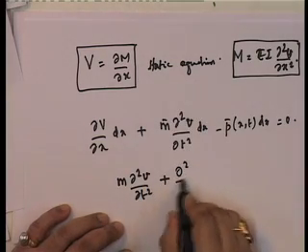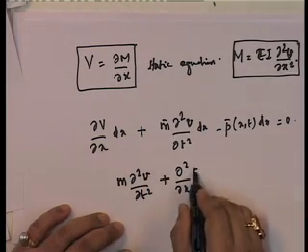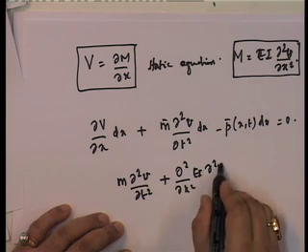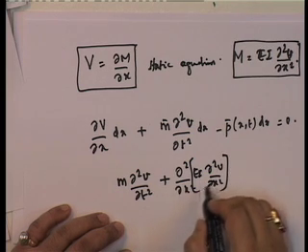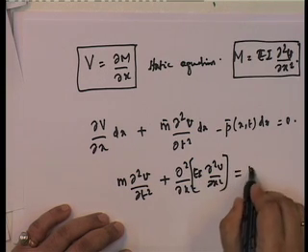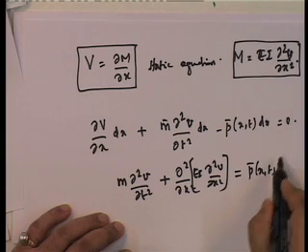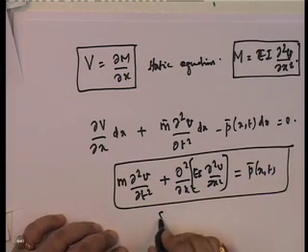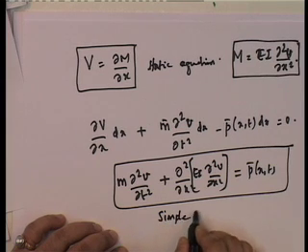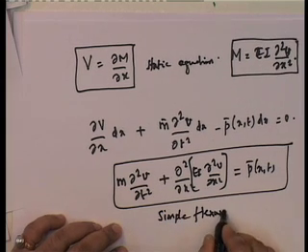So, this becomes del squared x of E I del squared v by del x squared, right, equal to p bar x of t. This is the simple flexural deformations.